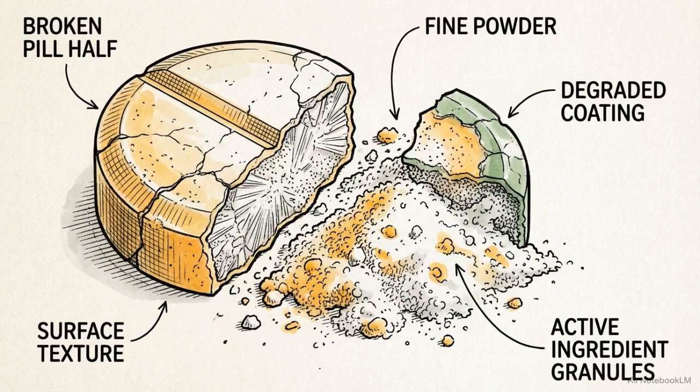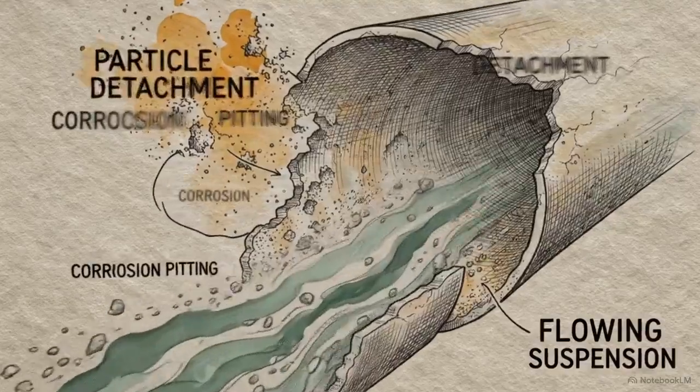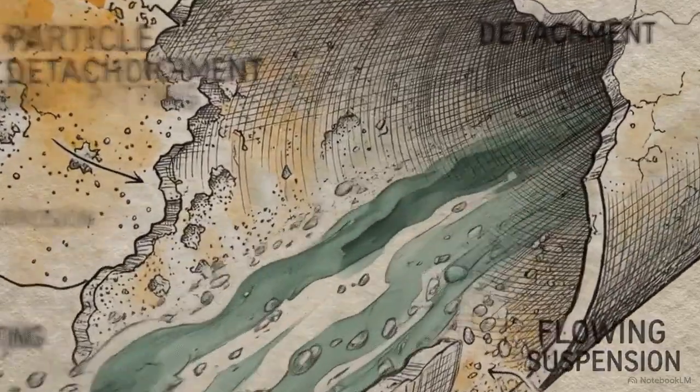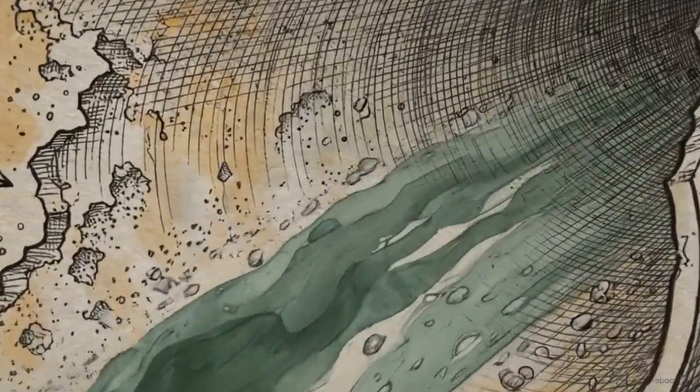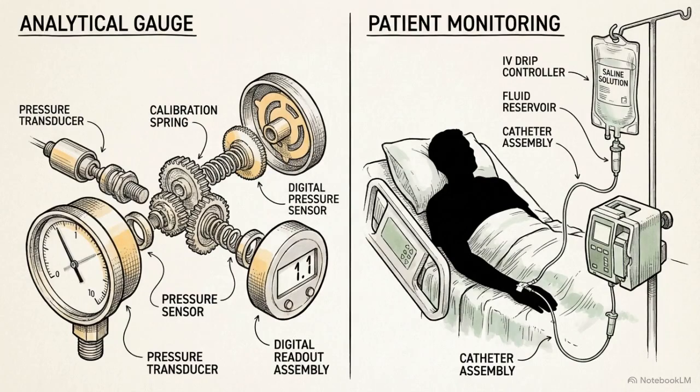The consequences extend past compliance data. Excess ions in the water actively catalyze drug degradation, threatening the stability of the final product. Elevated conductivity also indicates the water has become aggressive. This water can leach heavy metals from the stainless steel distribution piping and carry them into the manufactured batch. An upward conductivity trend, even while mathematically below the failure limit, presents a direct, measurable threat to medicine safety and patient lives.